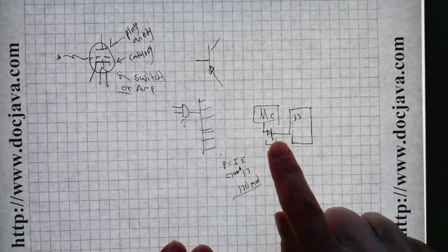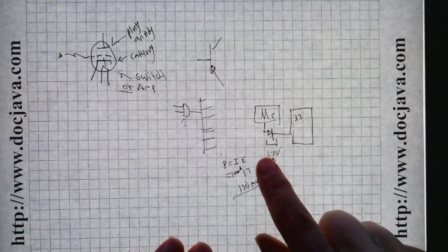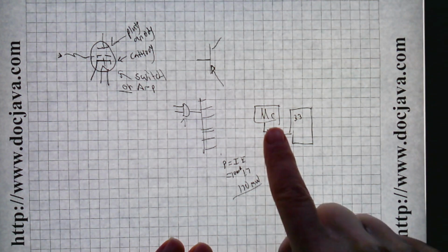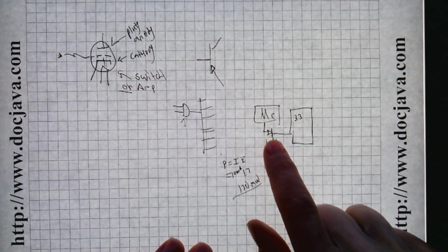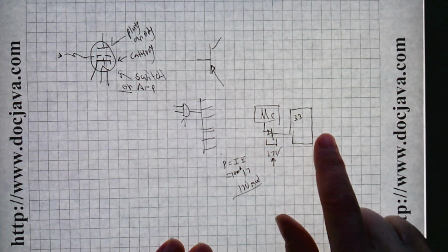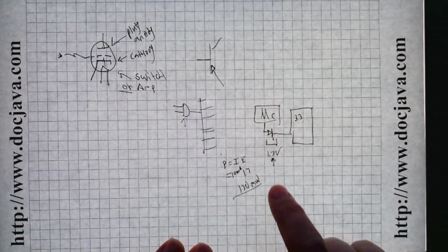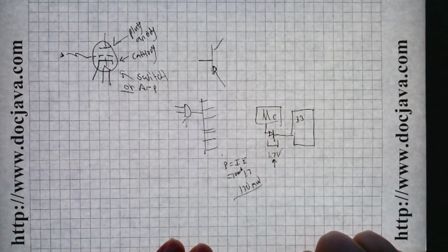So what happens to the diode? It's going to get hot and eventually burn out. And I'm like, you have to think about that stuff if you're going to just start throwing these parts in there. You can't just do that to a poor little diode. It's not meant for that. It's meant for detecting radio frequencies or something like this. It's meant to output microwatts, you know, 55 microwatts into a detector section for a little radio, not drive 170 milliwatts continuously. So you just burn it out and your whole thing will be broken.